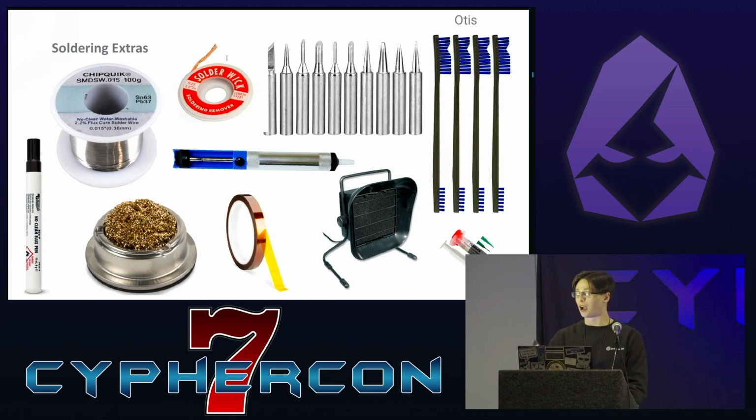And then finally, these Otis brushes, they're officially gun cleaning brushes, but I saw someone recommend them on Twitter for cleaning flux off of circuit boards, and they work really well with some isopropyl alcohol, so I wanted to throw those in here.